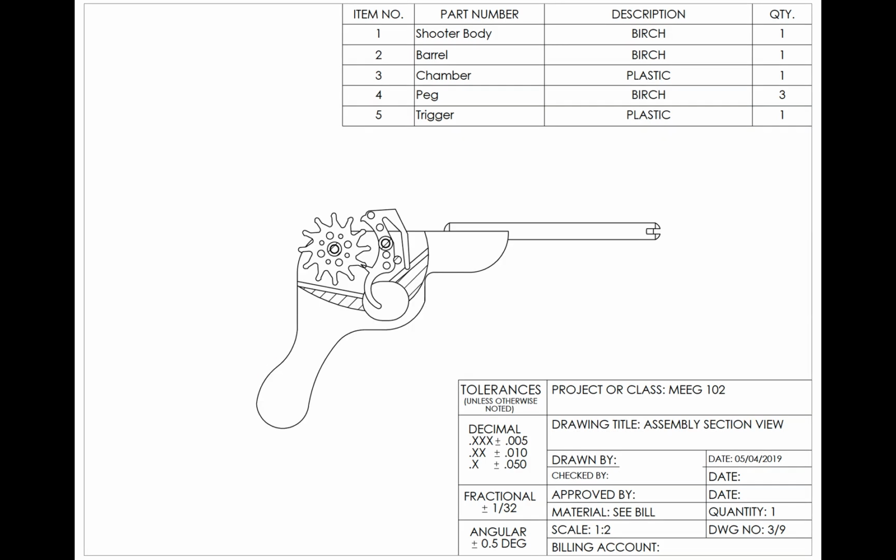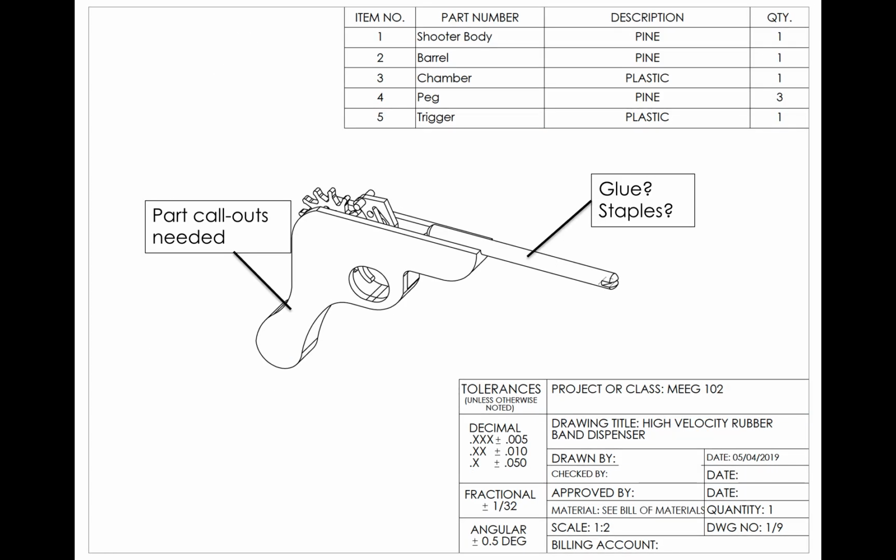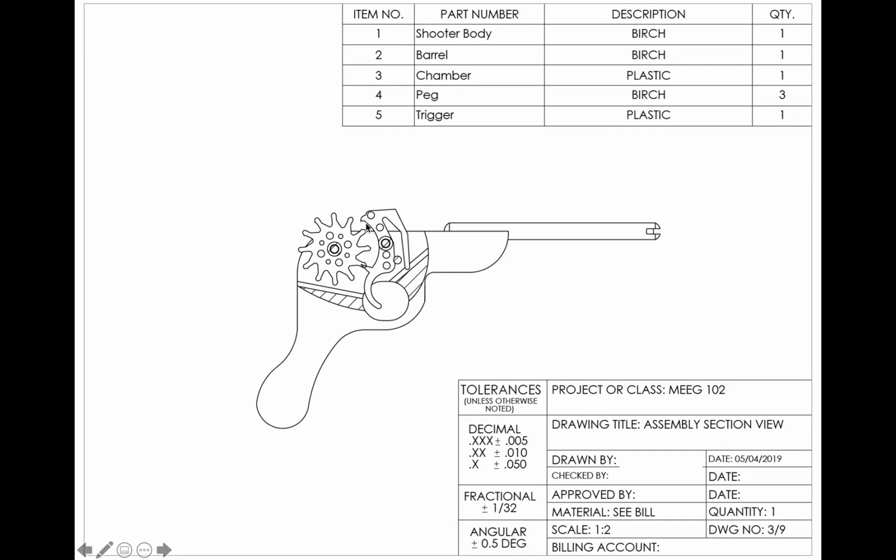All right, next up we have a broken out section view. Okay, so put me on pause and think about whether this is complete. All right, this was a really great addition. So if you go assembly, exploded assembly, broken out section view, this view here shows you exactly where those internal components are oriented. You're not going to get that off of the exploded assembly, and you're not going to get it off of this view. So this view is really nice to include in your packet, as they did a great job here as the third drawing. Okay, you could make it second or third, doesn't really matter, but to have that in the packet to show our folks who are manufacturing this exactly where these parts go.